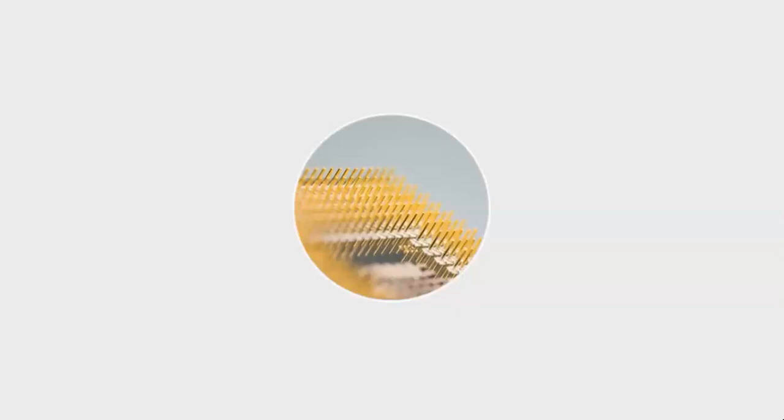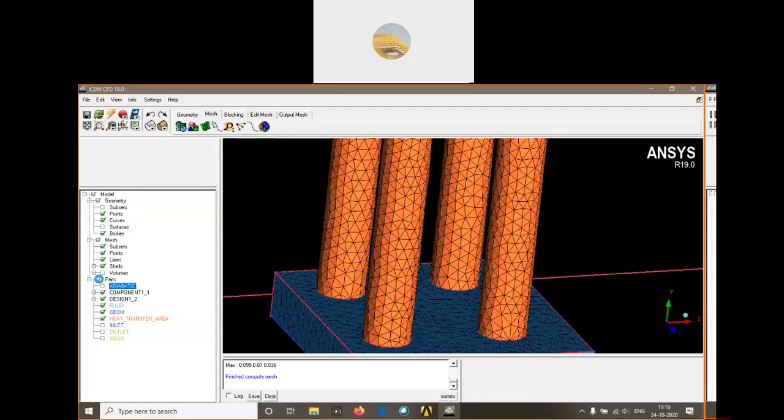Because if we further reduce our mesh size, it will take so much time. For this mesh we have around 10 lakh elements. If we go further, the solution time will be very high. So now what I'm going to do is follow another principle. I'm going to use another strategy to smooth the mesh. So let's see how to do that.